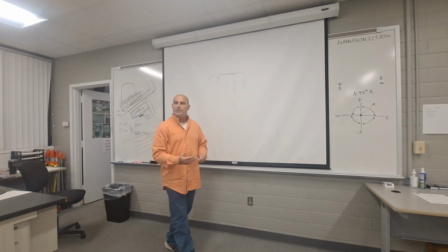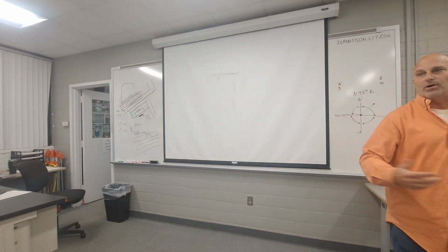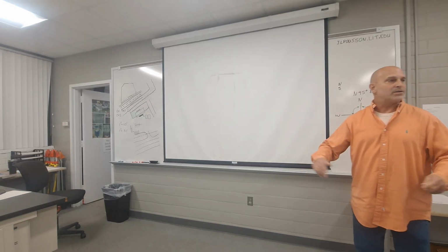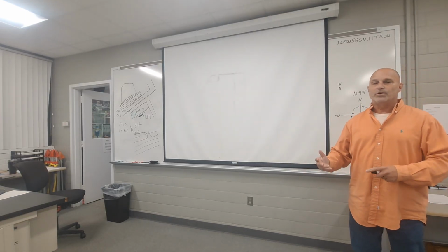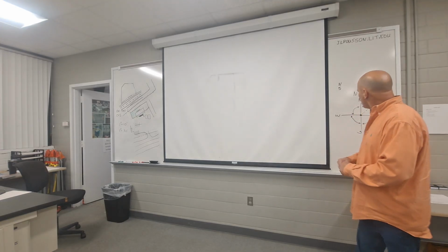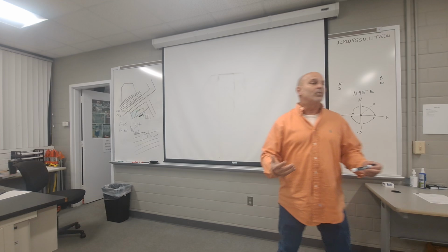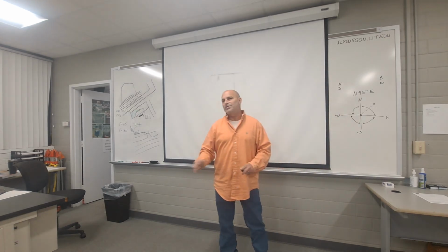Azimuth, you'll find that on some stuff that you go look at. It's not used in most of the stuff around here on properties, plot plans, plats, they call them. When you look up deeds and stuff, it's given in surveyor's units, normally in bearings like this. Azimuth is kind of like what we grew up with. That AutoCAD said, no, it's not like that anymore.